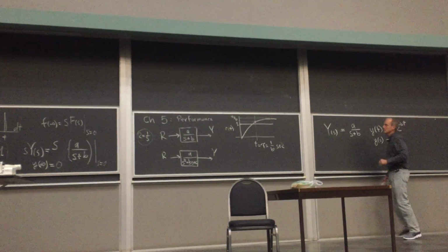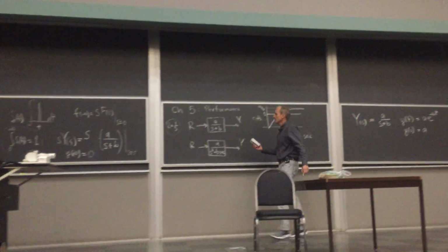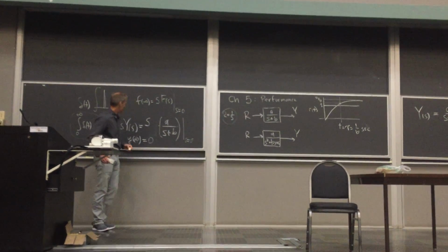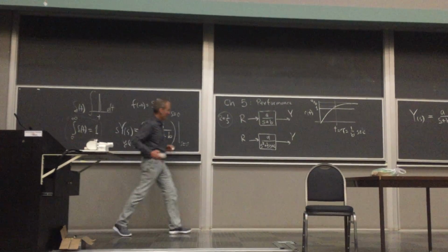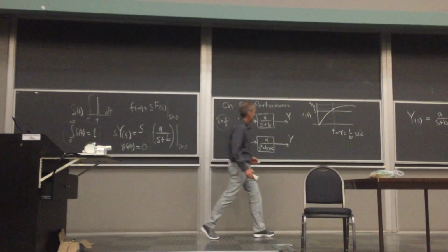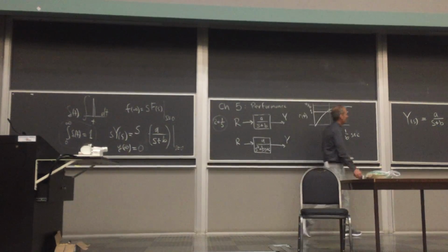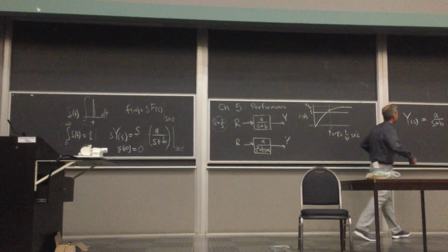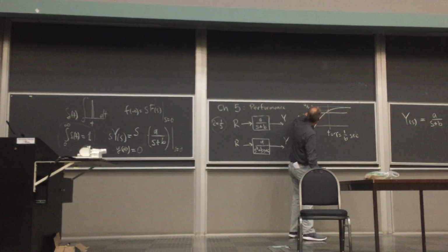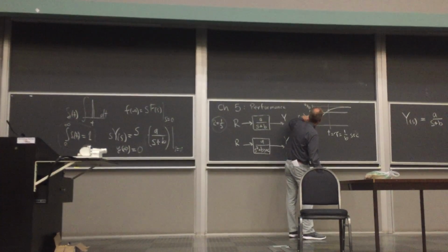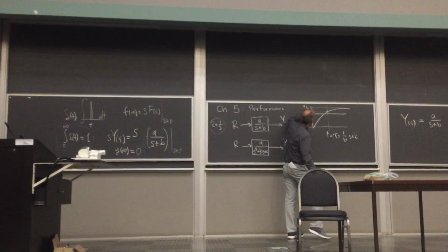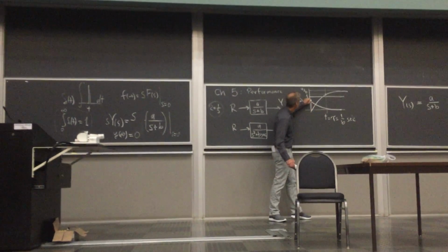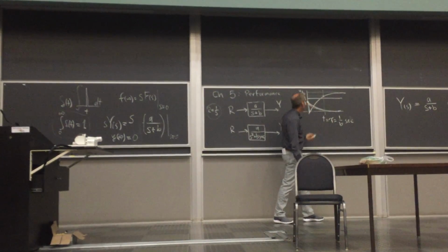Okay, so what's y at time 0? A. So what it says is that even though the initial conditions are assumed to be 0, when you kick it with a hammer, an impulse, it gives you an initial condition. It's like giving it an initial condition, so this could be A, I don't know what value it is, but say it's there, and it's going to exponentially go to 0. So with an impulse input, it goes to 0 exponentially.